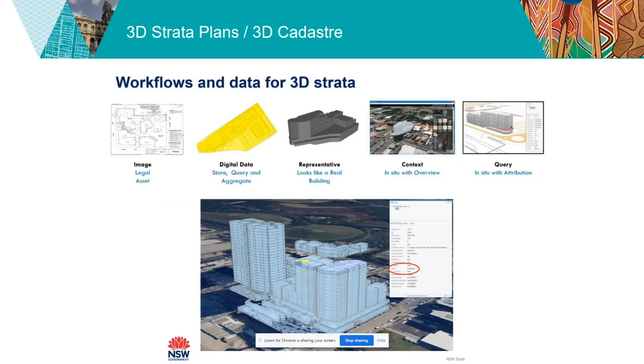On a plan, individual apartments might refer to height above ground, without that ground point being clearly defined. The position of an individual unit might refer to the center or edge of the wall casement, not an easting, northing and elevation in 3D space. Although this dataset is not remotely sensed, or a remotely sensed as-built representation of the building shell, it does have tremendous applications in the GIS world, or even for the general public.